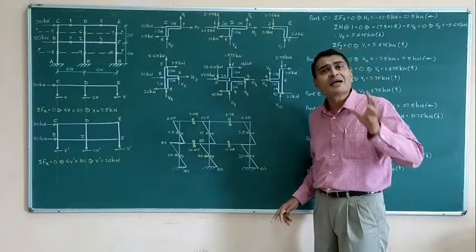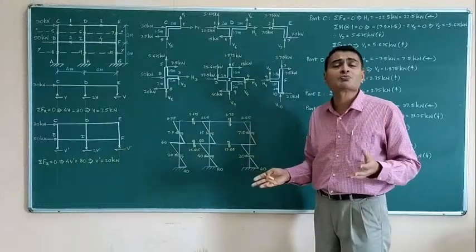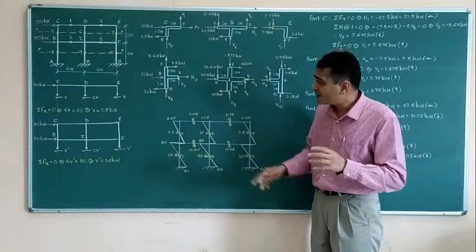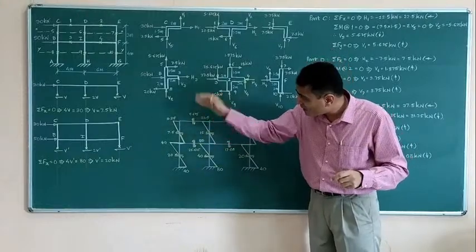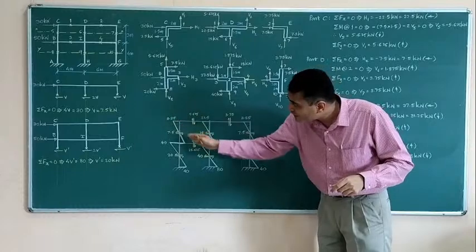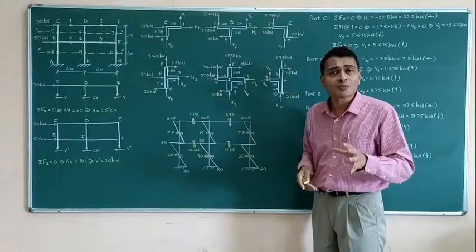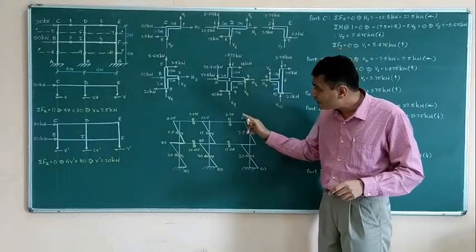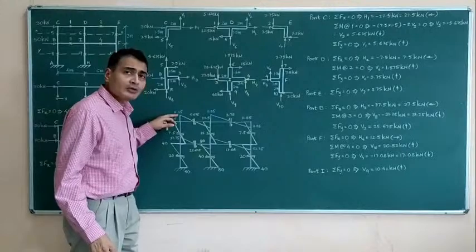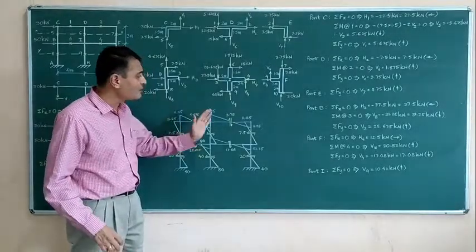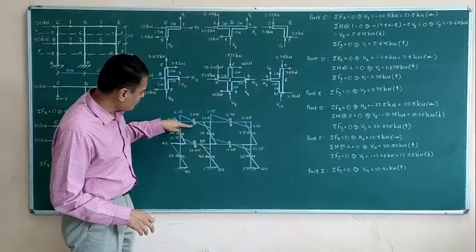So developing the moment diagram is also very simple. They are all going to be linear variations because we have point loads acting, and then simply use the values and the sense of shear force, sagging above, hogging below, and linear variation. You get the BM diagram for columns. Similarly, I will draw the BM diagram for beams. These blue colored lines are showing bending moment variation in beams. The same methodology has been used.